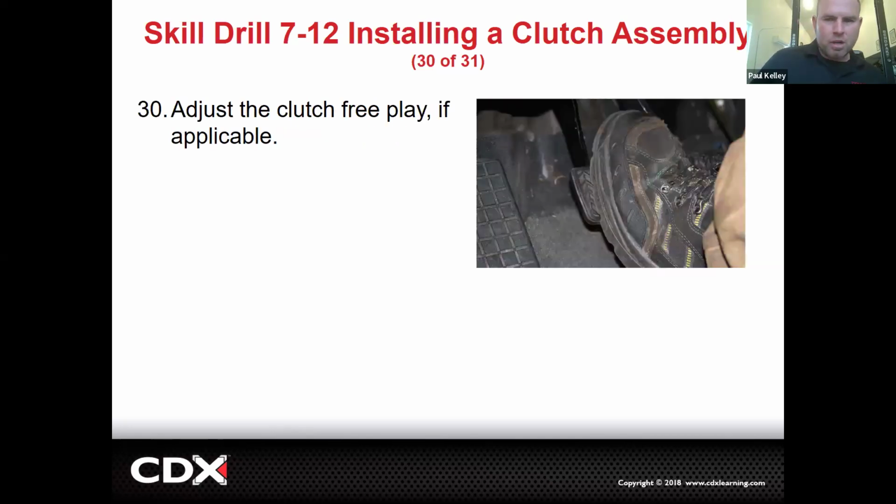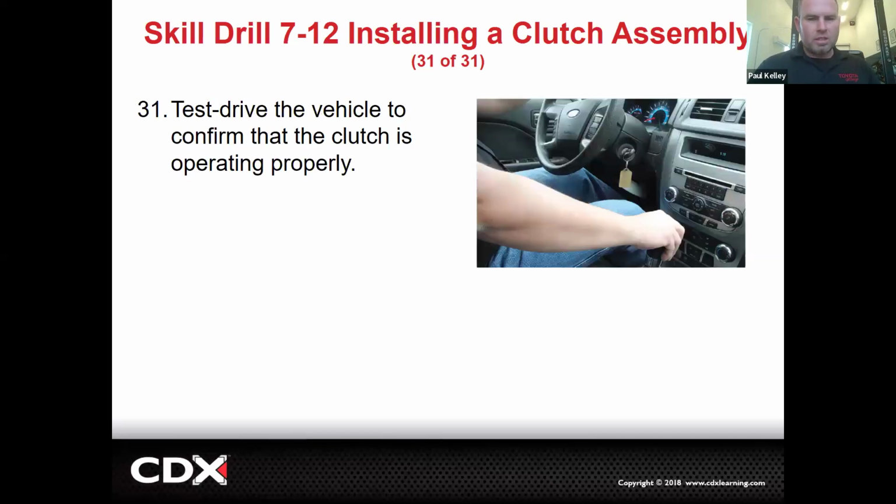And if you have to bleed it, I'm sorry, but if not, good. You should do a final check by verifying the clutch free play. If the free play is not right, think twice before you start adjusting because the free play shouldn't really change on a hydraulic clutch. And then of course, you're going to road test it, make sure the clutch grabs, make sure it holds, make sure it feels smooth, put a little bit of miles on there.